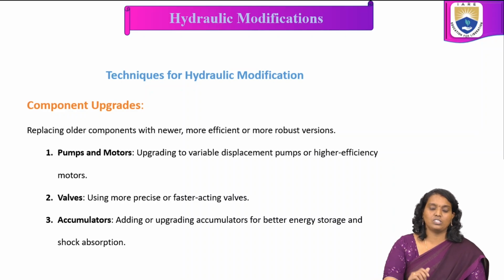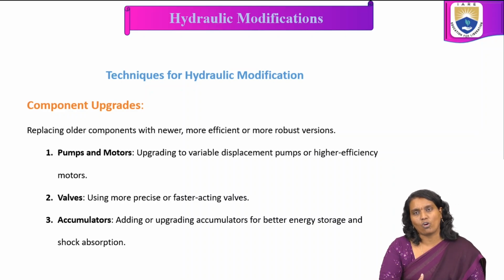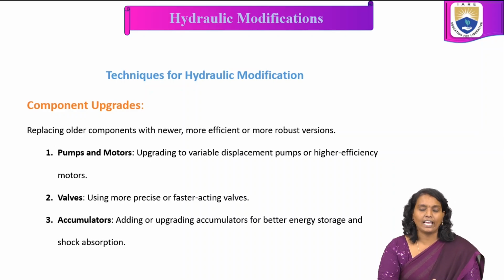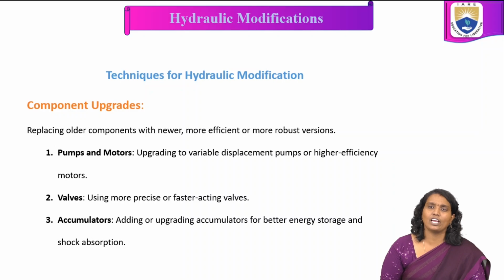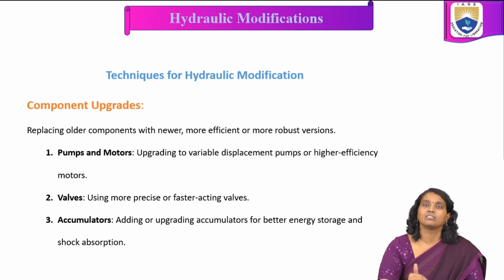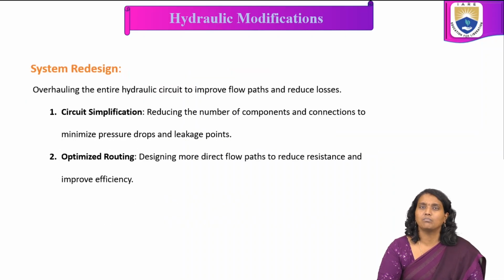Valves: using faster acting valves and precise ones also come under these component upgrades. So this is also one of the techniques for hydraulic modification. And accumulators: adding or upgrading accumulators for better energy storage and shock absorption. So these are the component upgrades, one of the techniques for hydraulic modification.